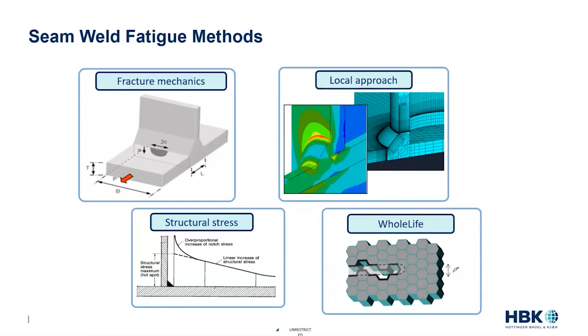So we're left with the final solution typically is a structural stress solution. And all a structural stress is a way to get a nominal stress out of my part, either realistically on our physical part with things like strain gauges or virtually on an FE model. But it's a way to recover a stress that may not be the actual stress at the weld toe or weld root, but it's a stress that's very repeatable and can be used as a damage measure. And we're going to see that in the next slide.